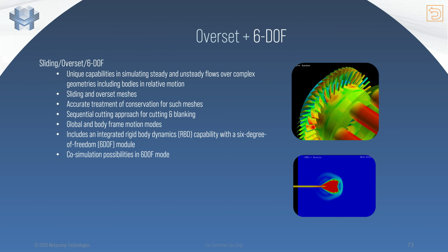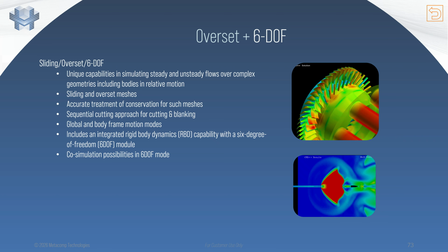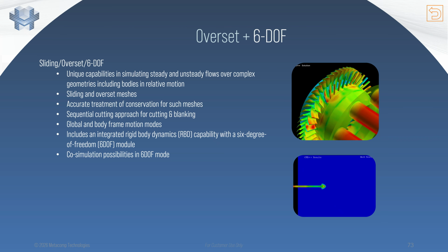CFD++ offers a range of powerful capabilities for simulating both steady and unsteady flows over complex geometries. It supports simulations with sliding and overset meshes, providing flexibility in handling dynamic configurations. Its sequential cutting approach enables multi-step cutting and blanking, making it a versatile tool for various engineering applications. Both global and body frame motion modes can be utilized.